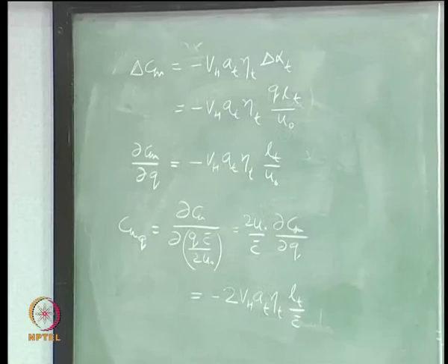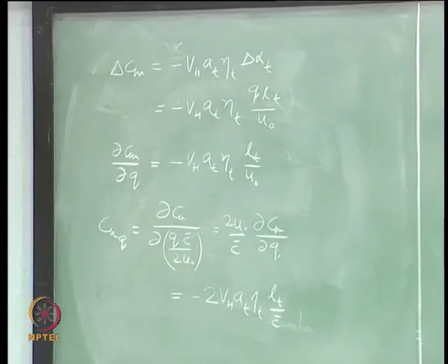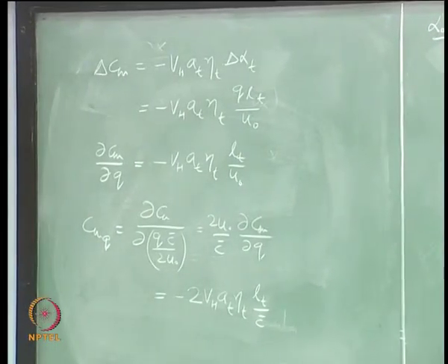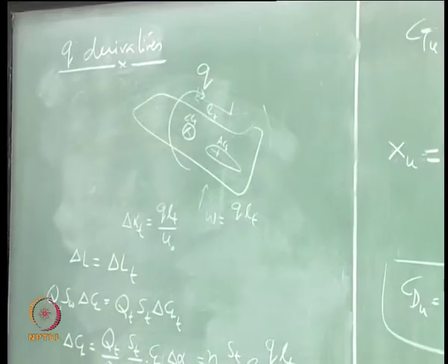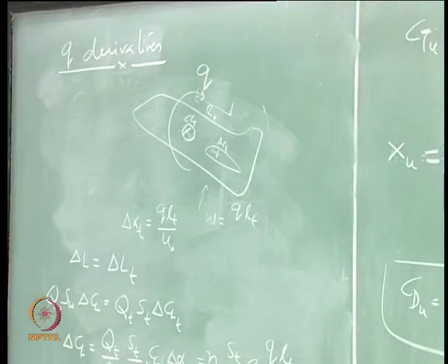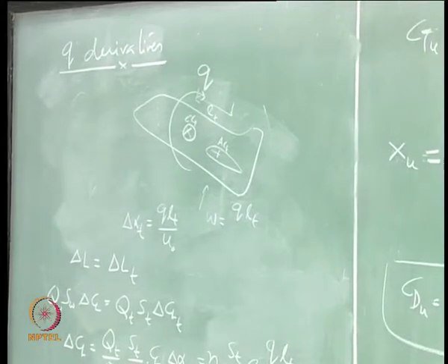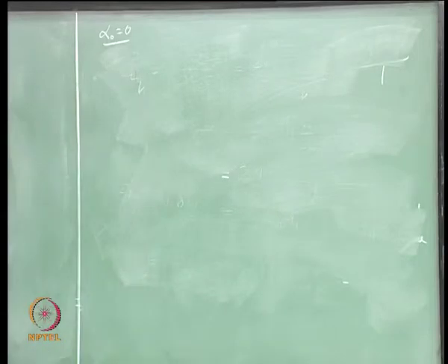Okay. So, this was a steady pitch rate, it is going to change angle of attack at the tail, but there is another derivative which looks similar to this, is due to the unsteadiness in the flow. Okay.